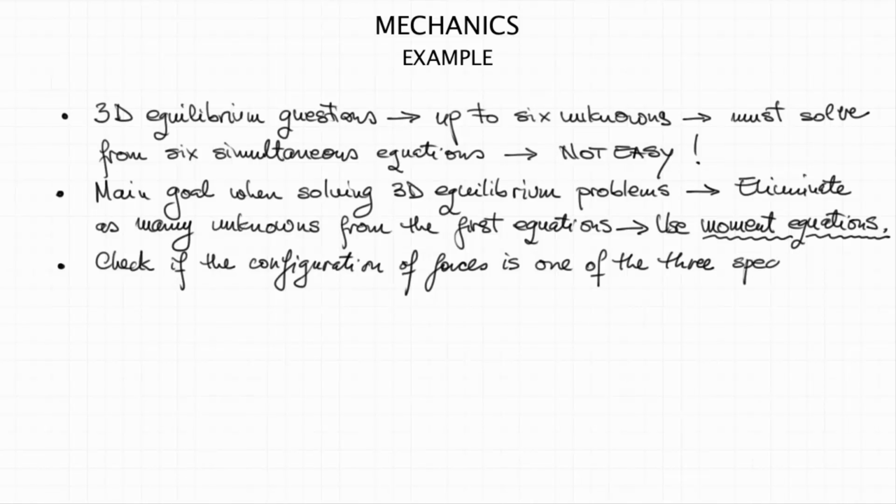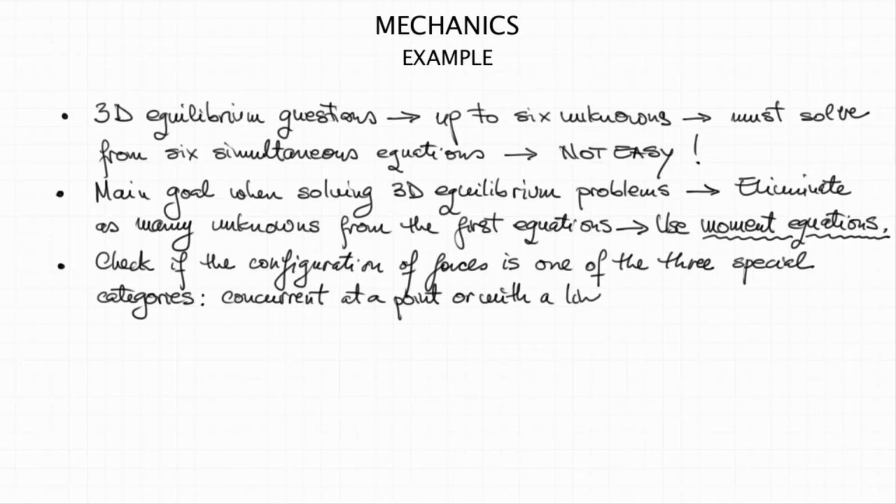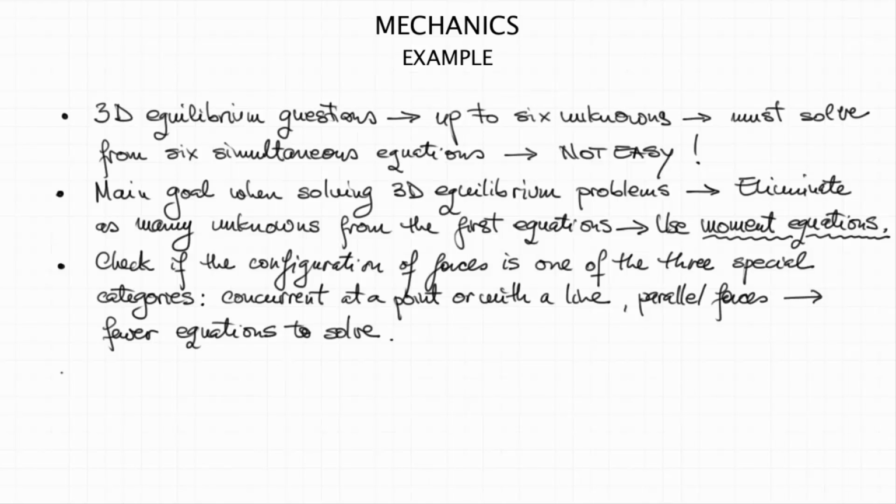There were 3 special categories: all forces concurrent at a point, all forces concurrent with a line, or all forces parallel. If you recognize one of these situations, that's excellent, because you will have fewer equations of equilibrium to solve. That would simplify your task significantly.